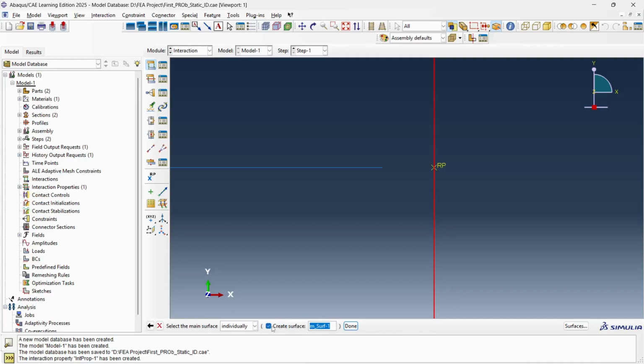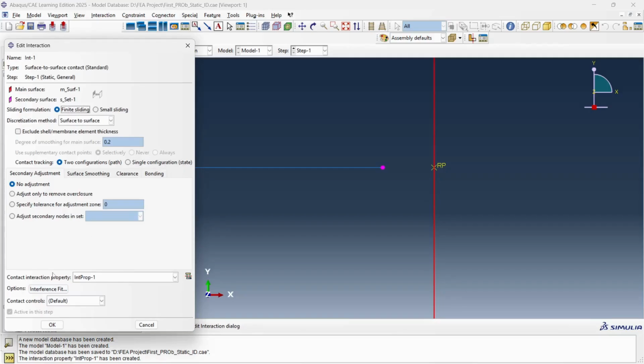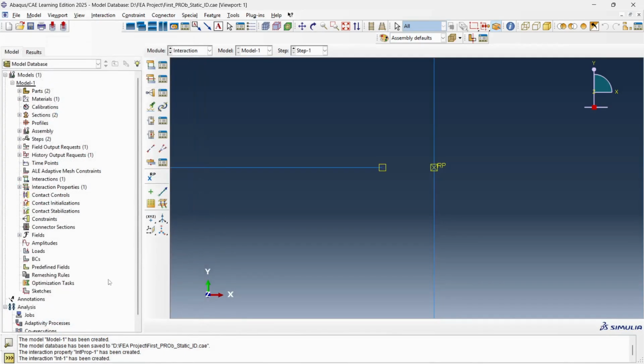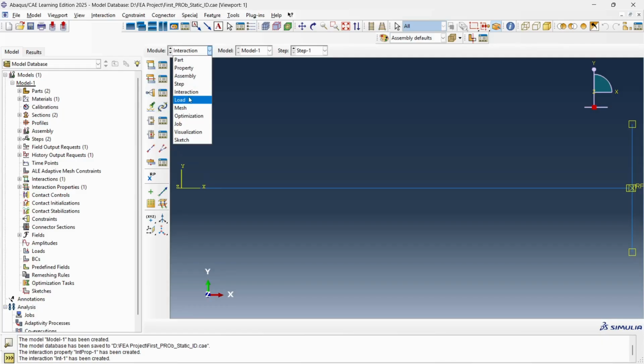And we click on this surface. Okay, just click on done. Now choose the side for the edges. We'll click on yellow and then choose the secondary type. So the interaction is between this point and this point. So we'll click node region and this is our node. Done. Let the things be default here. Just click OK. You will see in the messages that the interaction has been created. Now we'll click on this auto fit view so that things come into the view. We are done here.